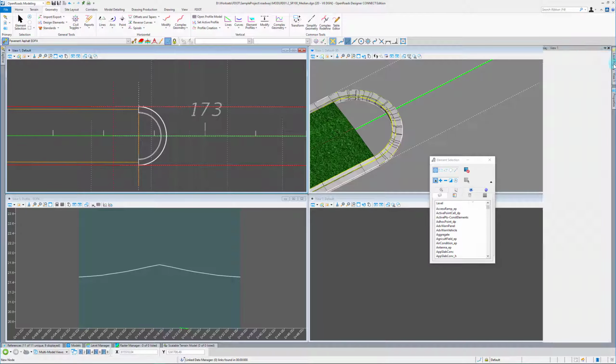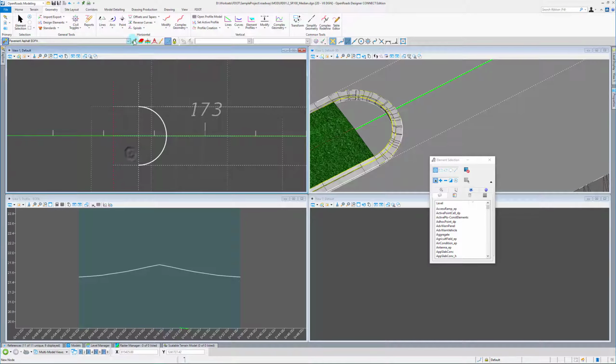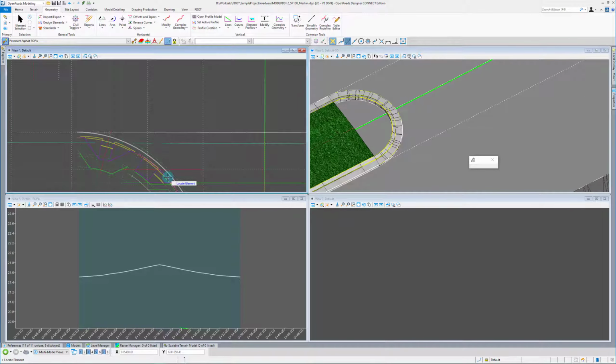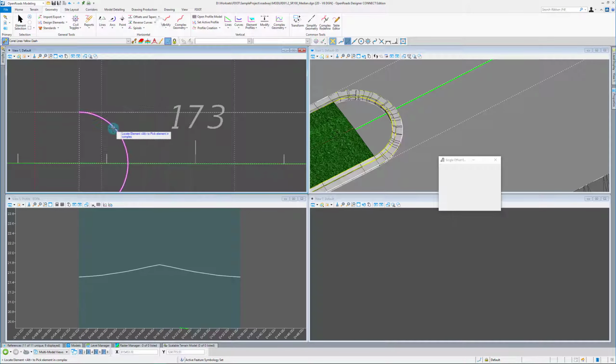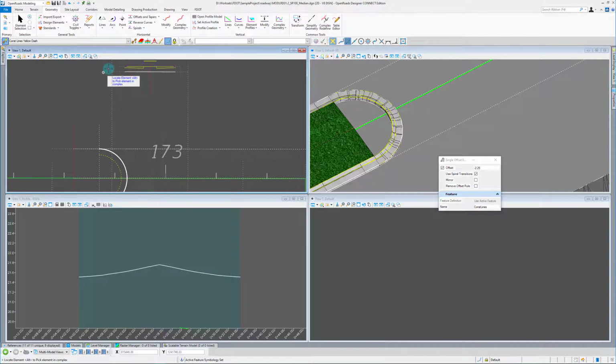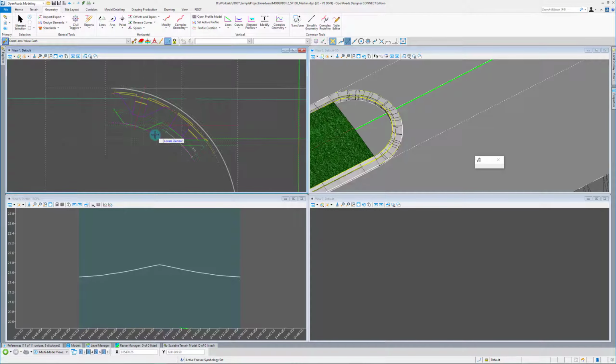So I'm going to go ahead and turn off all this stuff since we've set that. And we're going to grab our yellow dash because we're going to start modeling this curb. So I'm going to single offset 2.25 because this is E curb in the middle here. So I've got that. And we're going to get our green. Where's my green? I got green dash. Let's get green solid.